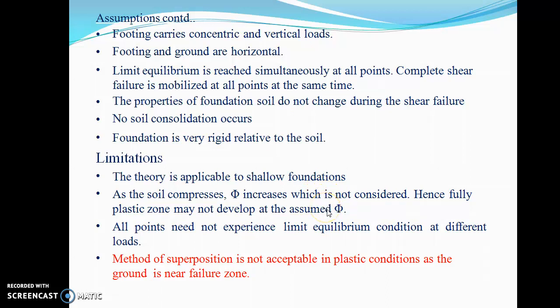We do not give the benefit to the soil of getting a little higher density with respect to time. We assume that the properties are going to remain same at all times. That is what we basically mean by the assumption of homogeneous soils. We also assume that there is no consolidation occurring inside the soil. Foundation is very rigid as compared to that of soil.